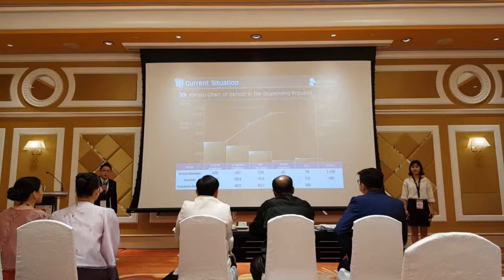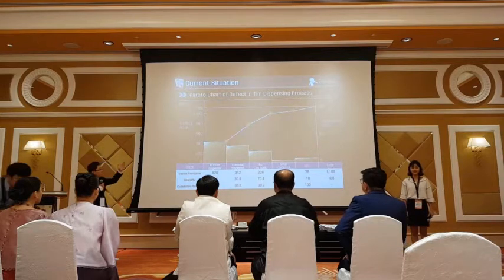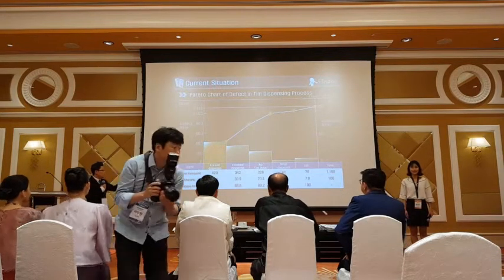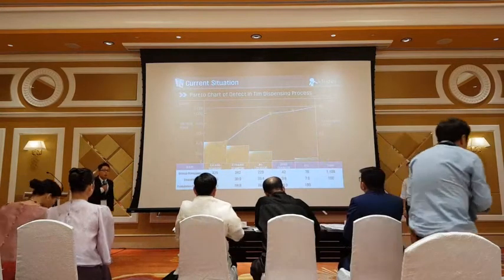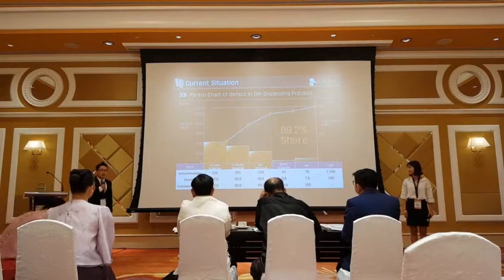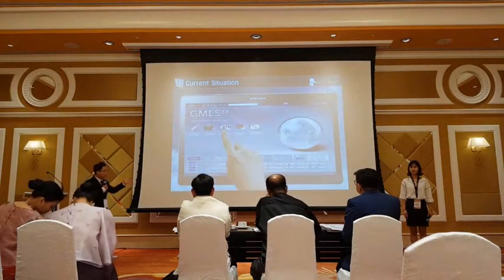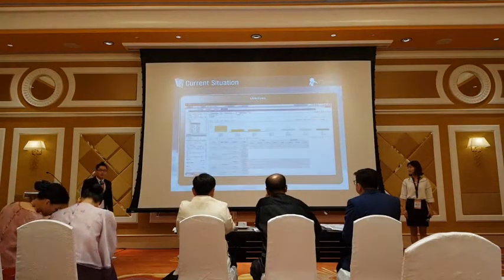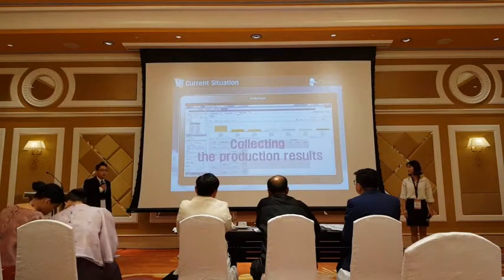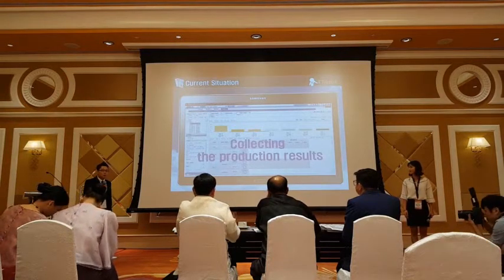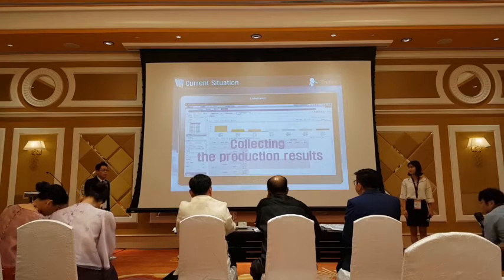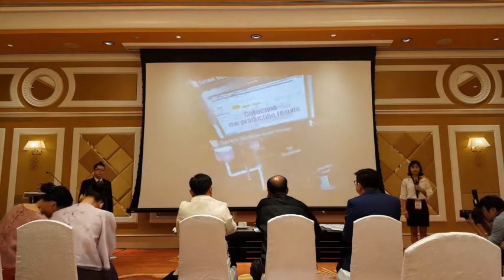As a result of analyzing the defect rate of dispensing thin liquid, exceed dispensing, irregular dispensing, and low thin liquid defect account for 89.2%. We collected data from process management in GMS system, and we analyzed it using ultra-high-speed camera, viscosity meter, and electron microscope.